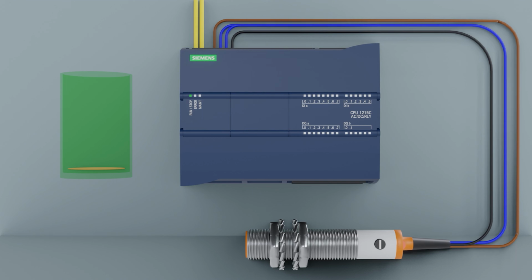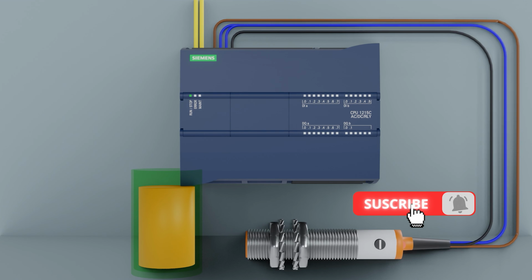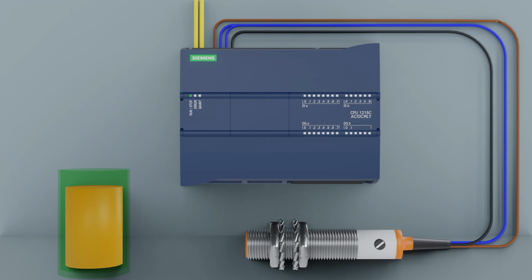We turn on the PLC, it is in run state. We are going to sense a glass of orange juice. We bring it close to the sensor. We calibrate the sensitivity. Input 0 of the PLC and the sensor indicator are activated. We move the glass away from it, and it stops sensing.